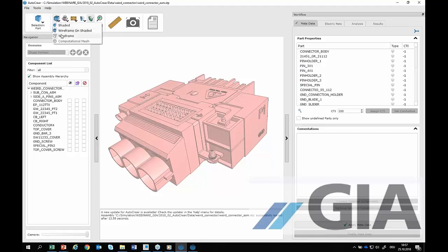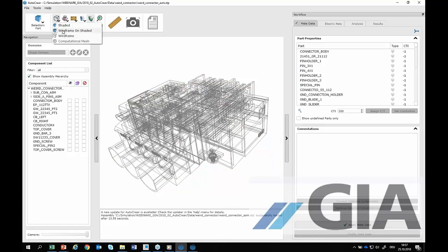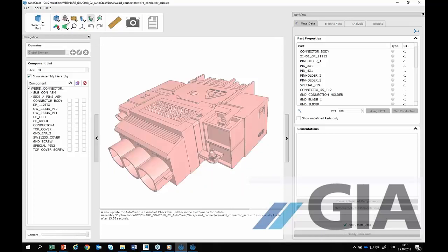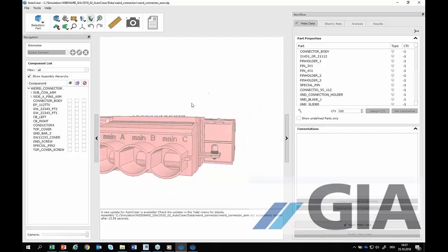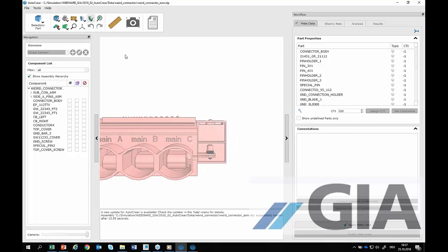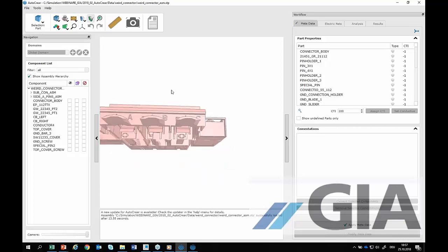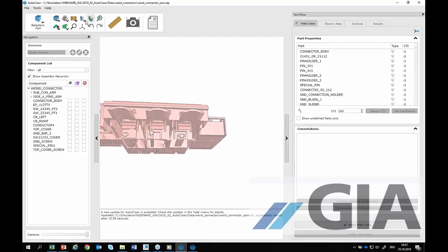Here we can change between wireframe and other shading modes. Here are special capabilities to spin around. When I want to see that component from the front, I type F8. Or here I have capabilities to bring in cross sections, and take them out again.